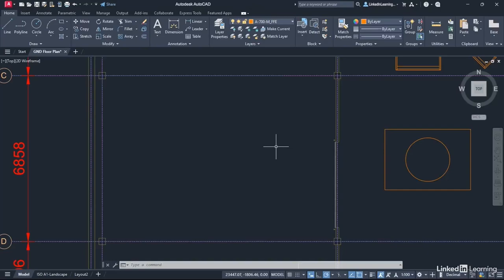polar. Come down to the status bar. There's polar tracking there. Ortho is this one. It's a little right angle symbol. Click on it and you'll notice that polar automatically turns off. You cannot run polar at the same time as ortho and vice versa. So we've got ortho switched on now. Let's go back to that polyline command here on the draw panel. I'll pick a similar point as last time for the start point, left click.